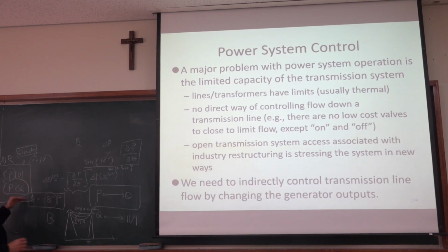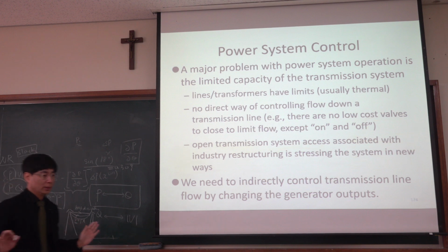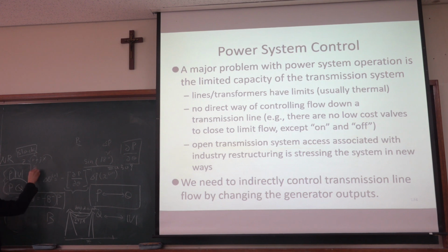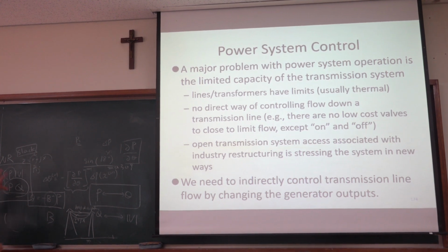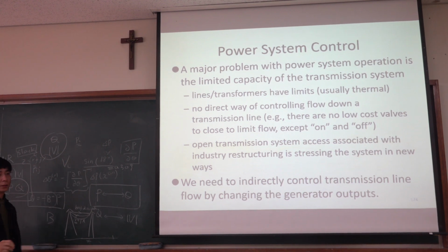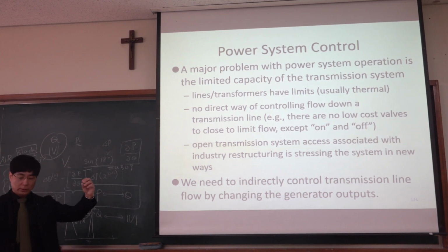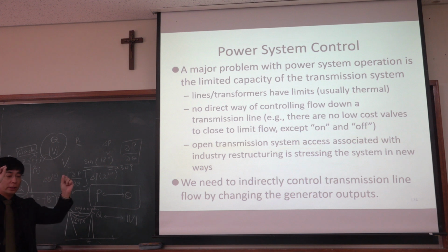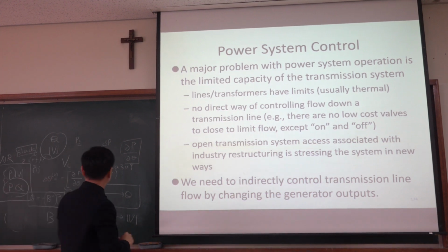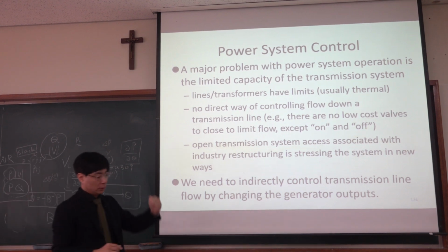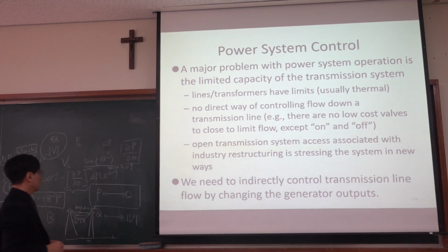But when you solve this equation, we do not have that constraint. In reality, we have the constraint. So when you solve this power flow equation, you determine theta and V, or simply the complex voltage at each node, right? Then we have a topology, we know the complex voltage, and then we can determine the current on each line and the complex power on that line, right? But if there is too much power flow on some line that exceeds the limit of the transmission line, heat is generated, okay? So that's a problem.